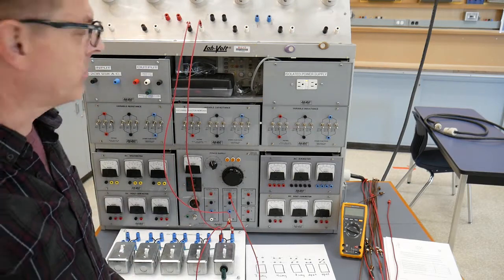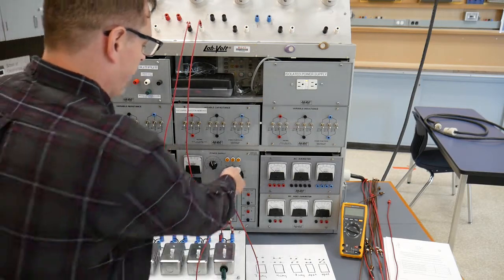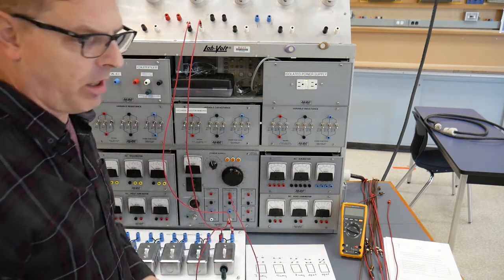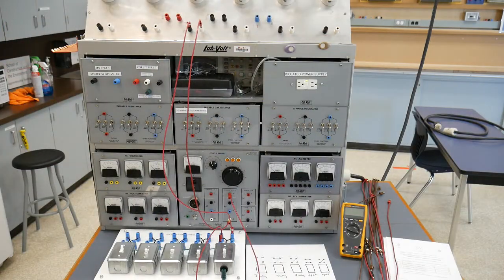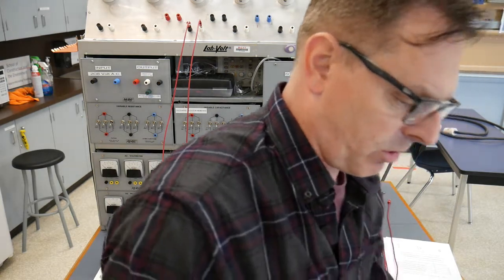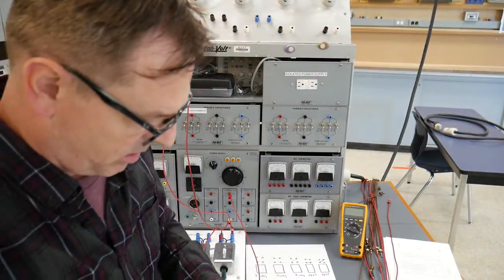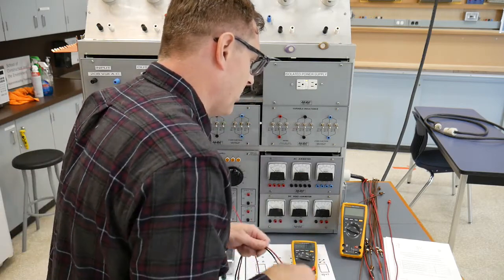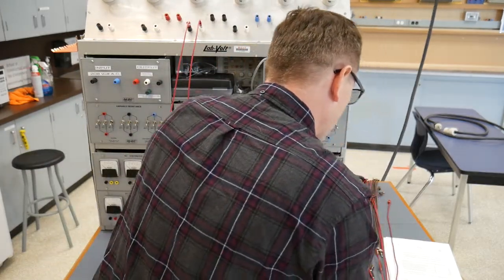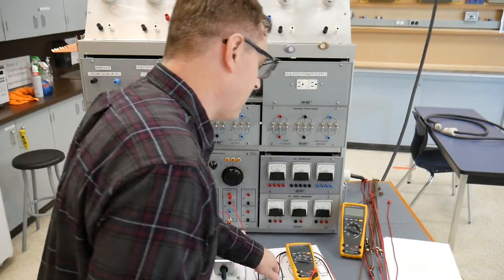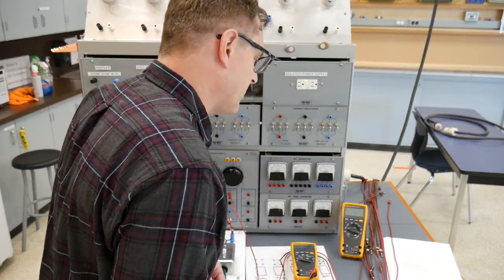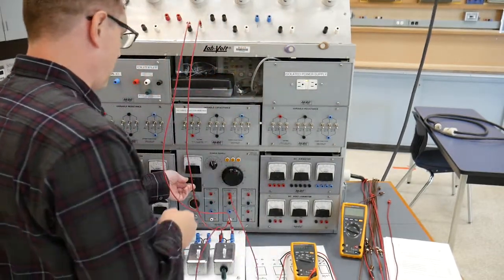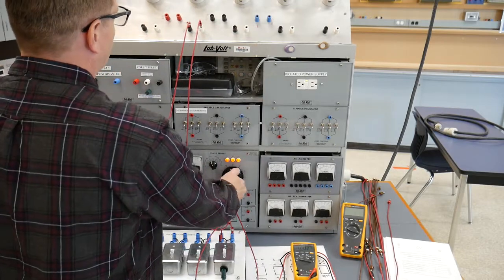Okay, so with that, I'm going to make sure that's zeroed off. Going to grab my meter because they're going to ask us to measure the voltage across the switch here, I think. So I'm in volts AC. Ensure that the main breaker on the power bench is off, connect it up, and then step 5 is turn on the main breaker, your power, and demonstrate the action of your circuit. So I'm going to turn it on. I'm going to turn my volume up.